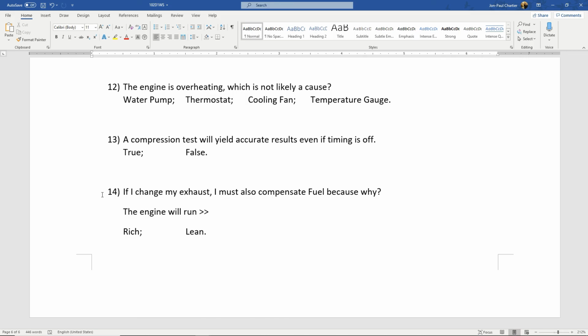And then it detonates. So step one, if any of you ask me, hey Mr. C, I want to build a race car. What's the first part I should buy for my Civic, my Mustang, my Challenger? It doesn't matter what it is. My answer will always be, you need to find whatever the solution is for air to fuel on your car. So on my Subaru, I'm very fortunate. The Cobb Accessport is a little module that I can buy, and it will tell the computer to change the air fuel ratio. And it's not very expensive. Otherwise, you're looking at aftermarket computers to handle that. But in any case, I always run with that first.